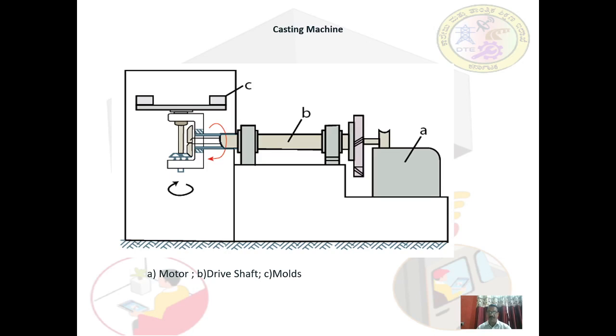In the manufacture of thick-walled symmetrical structures such as pipes and sockets, centrifugal casting may be used. A partially filled mold is rotated rapidly about a central axis. Centrifugal force presses the material outward into the mold, and in the process the material gets compacted. This is about cast molding.